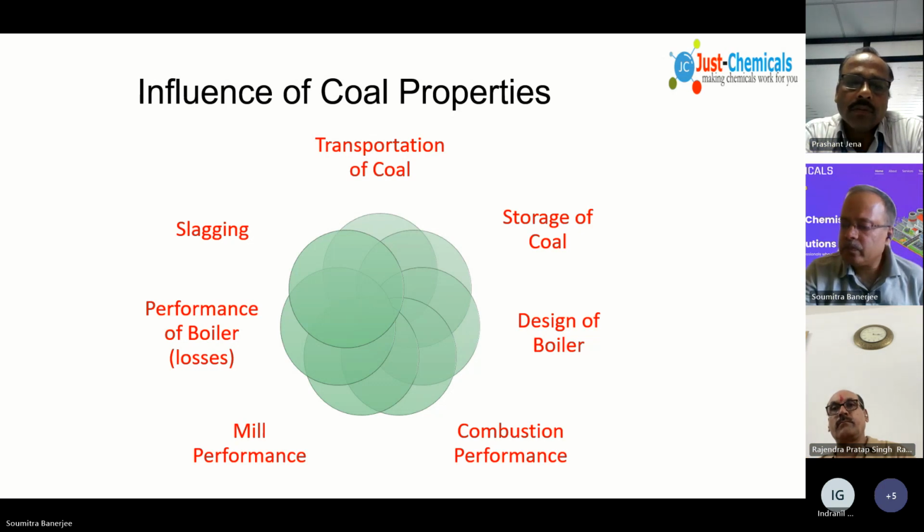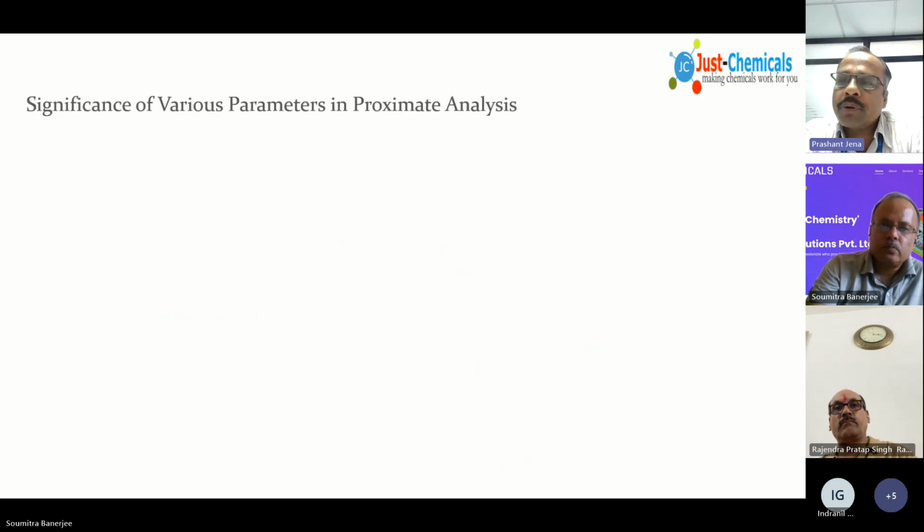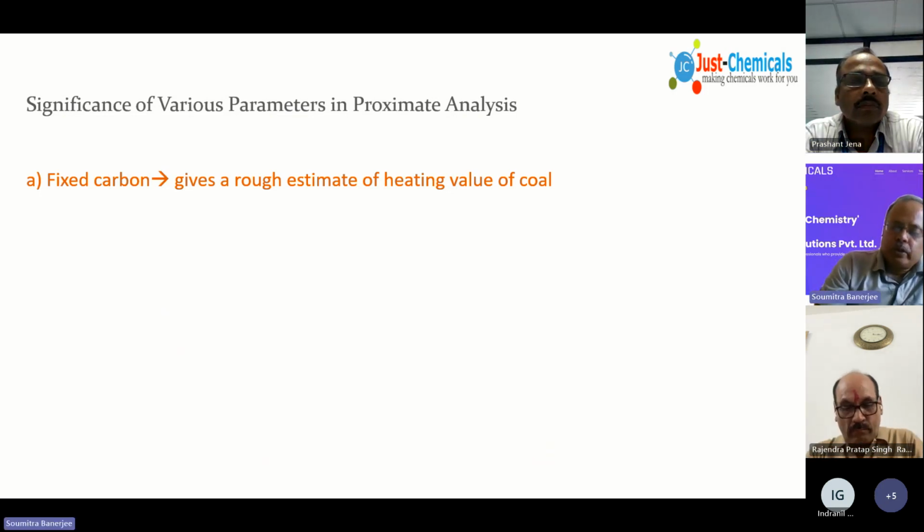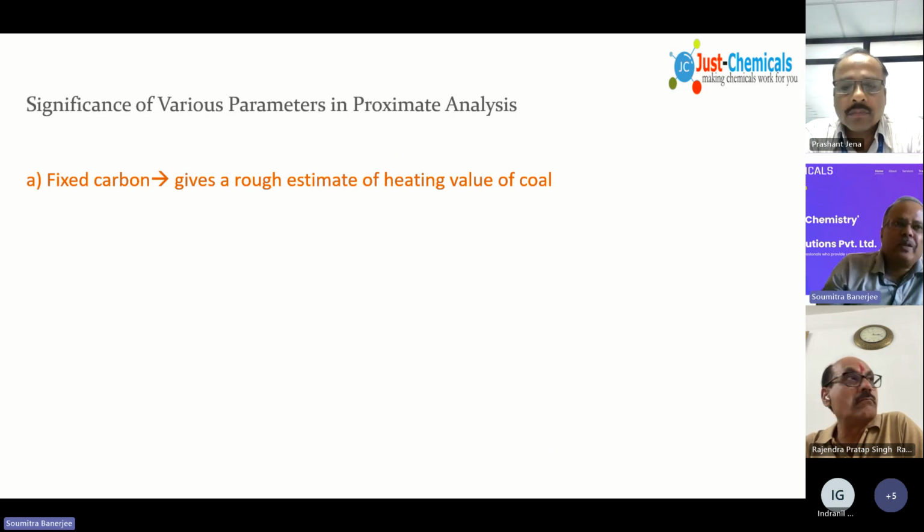Achha. Are they using Indian coal or imported coal? Imported, sir. That's why. That is the problem, actually. So the VM goes out, sir, and the remaining carbon becomes char, and that charring is the problem there. That is like slagging inside the bottom place.